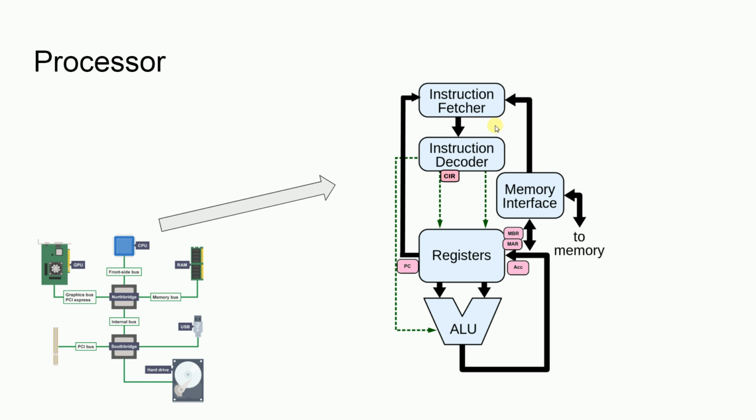So what we have is an instruction system which consists of the program counter. That is a register. A register is just a piece of memory, very fast memory that's stored within the processor itself. It's got its own set of values. The program counter says where to go and get some information from. The memory interface will then pull down that instruction that's at the program counter, and quite often a bit of data with it as well.